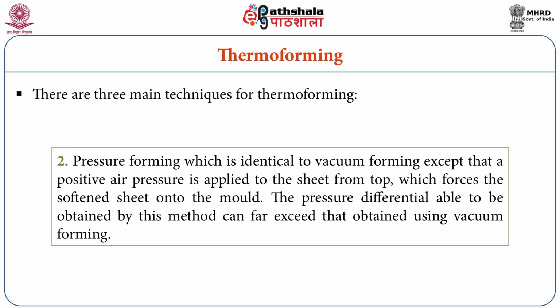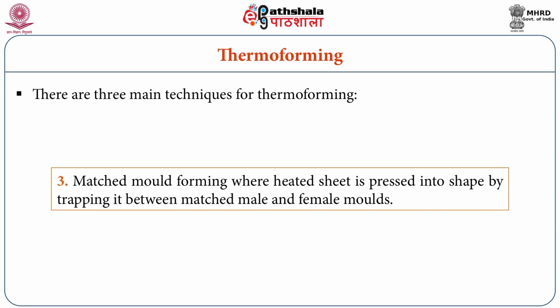Second one, pressure forming, which is identical to vacuum forming except that positive pressure is applied to the sheet from the top, which forces the softened sheet into the mold. The pressure differential obtainable by this method can far exceed that obtained using vacuum forming. Third one is matched mold forming, where the heated sheet is pressed into shape by trapping it between matched male and